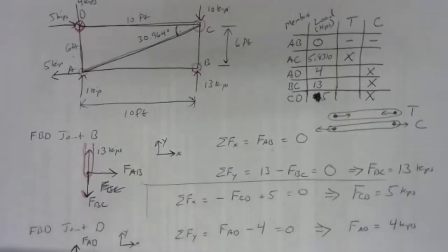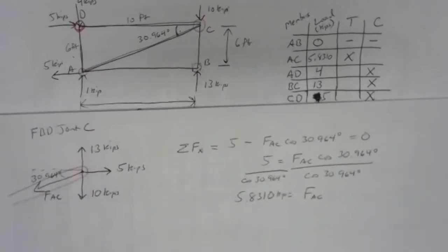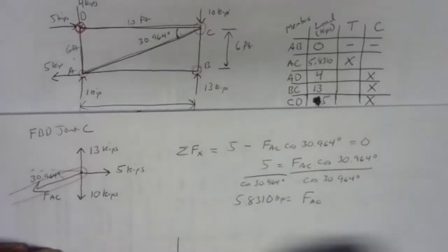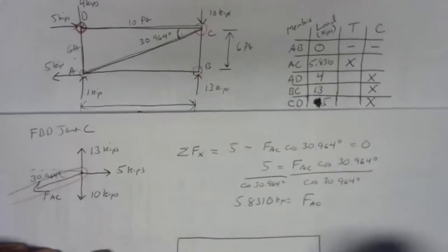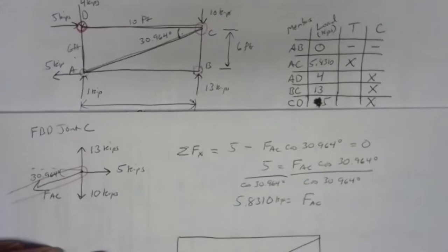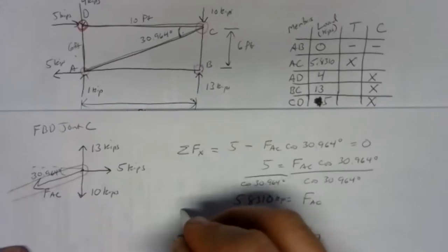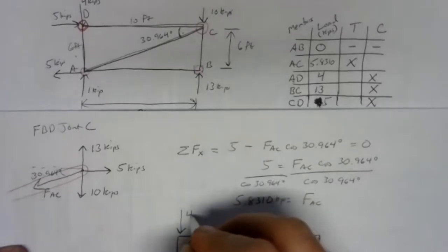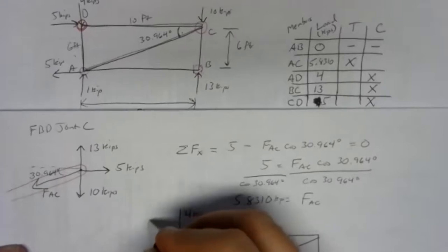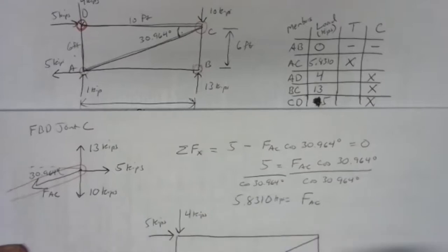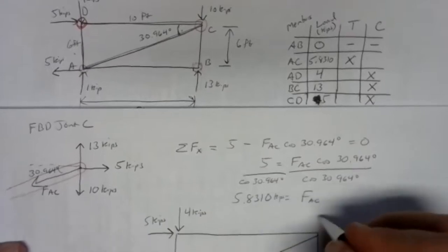Now to communicate our answer, it's a good idea to draw a force summary diagram. And the force summary diagram, it's usually a good idea to draw it as big as you can, because cramming it into little spaces on the page can be problematic. But that's where you put everything that you've calculated. Some people get fancy with it and draw different colors for the applied loads and the internal and external loads, but you don't need to do that. This is also a good place to round to your final number of significant figures.